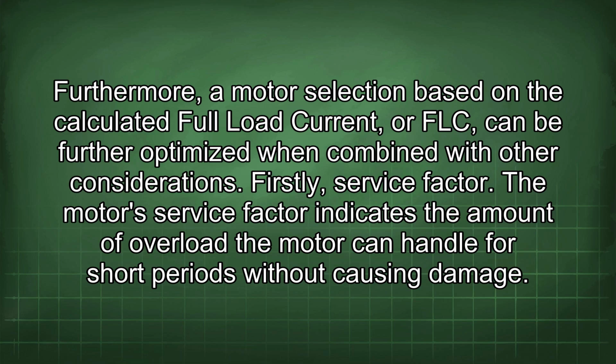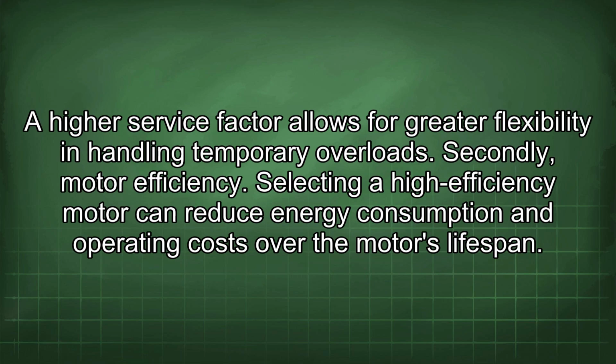Furthermore, a motor selection based on the calculated full load current, or FLC, can be further optimized when combined with other considerations. Firstly, service factor. The motor's service factor indicates the amount of overload the motor can handle for short periods without causing damage. A higher service factor allows for greater flexibility in handling temporary overloads.